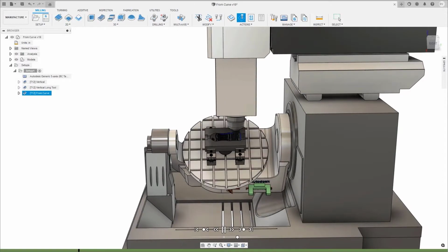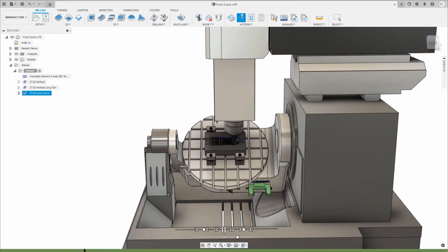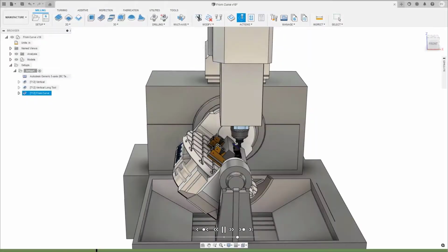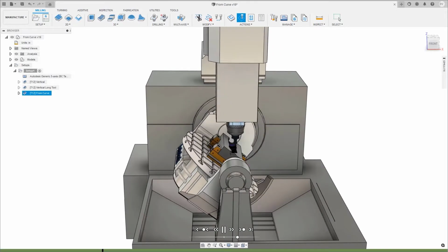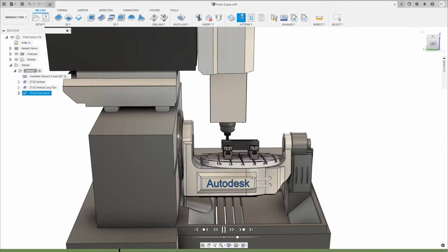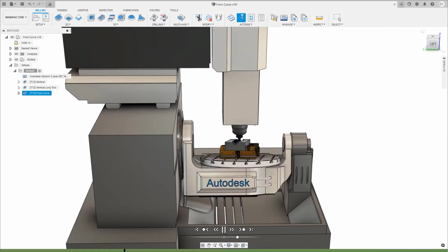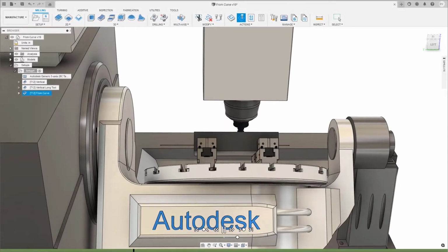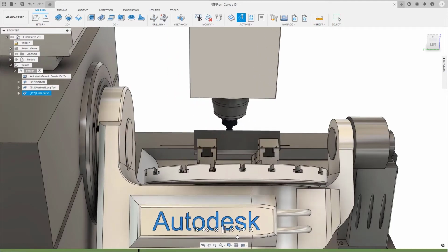The introduction of a 5-axis machine tool to your manufacturing process adds 2 additional rotary axes of control to the tool axis during the machining process. Using 5-axis machining can help minimize issues associated with multiple setups, poor cutting conditions, and interference with the machine or tool, which can occur during the part manufacturing.